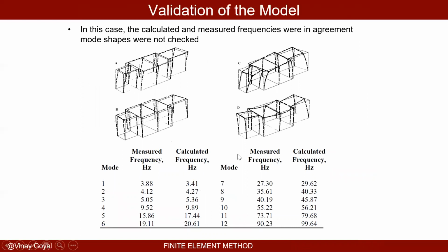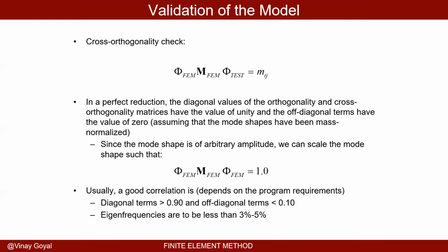Here you can see that in this case, the calculated and measured frequencies were in agreement. Now you don't see the mode shapes being checked, but that was checked. You can see here the measured frequency and the calculated frequency are not too bad across the board. You also want to check the mode shapes, right? We'll talk about that. So you want to do this check, the cross orthogonality check.